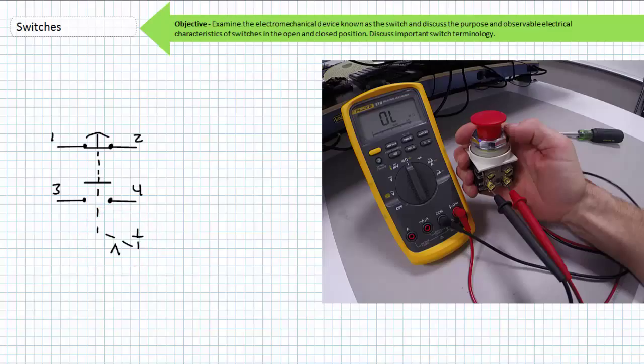A quick note on emergency stop buttons. Resetting an emergency stop isn't as simple as pulling the mushroom button back out. Normally they need to be rotated a half turn for it to reset. Sometimes the face of the button has an arrow to remind you of this necessity, sometimes it doesn't. Additionally, some emergency stop buttons have a green ring on the stalk of the mushroom button to indicate that the switch is in its deactivated or go state. Look at emergency stops from the side to make sure you see the green band before you return equipment to service.